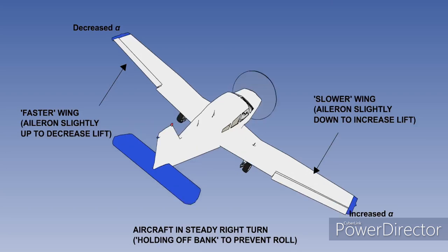In a climbing turn, the airspeed is likely to be lower, but with full or high power, and in a single propeller aircraft, the rolling and yawing forces from the propeller and its slipstream will add to the control deflections required for balanced flight, and may complicate the aircraft's reactions in a stall.